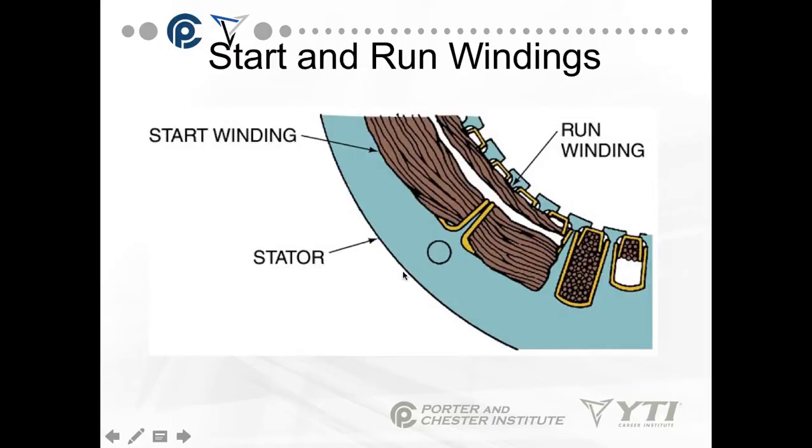Okay, when you take a close look at the stator, remember that's the fixed portion inside the motor, you have a run winding, which is made of some pretty thick wire, and there's not a lot of it there. But you'll also see a start winding in most motors. That start winding is a bigger bundle of thinner wire.